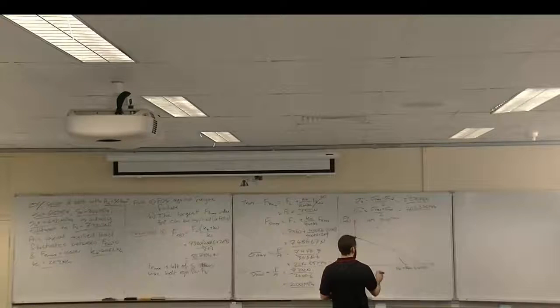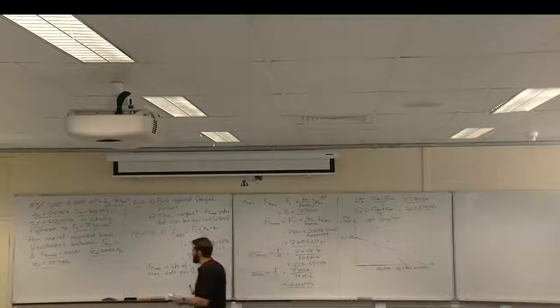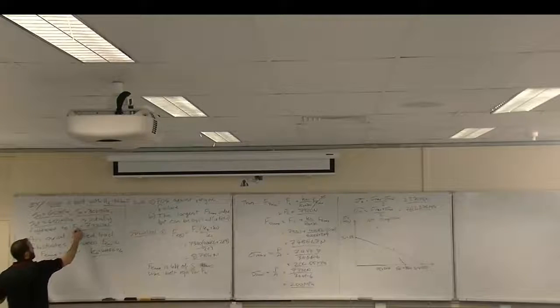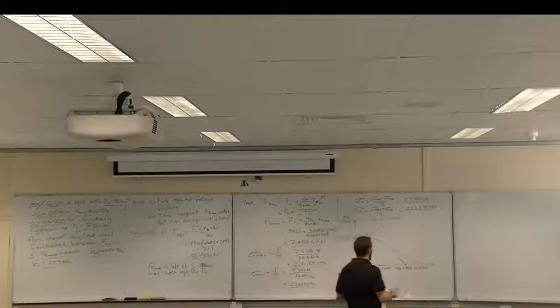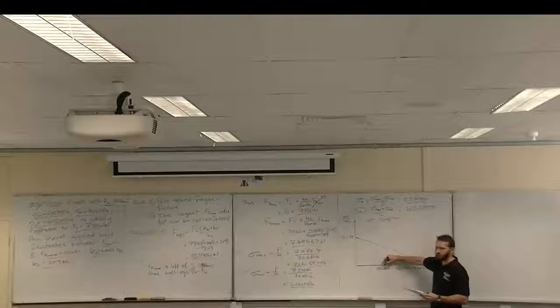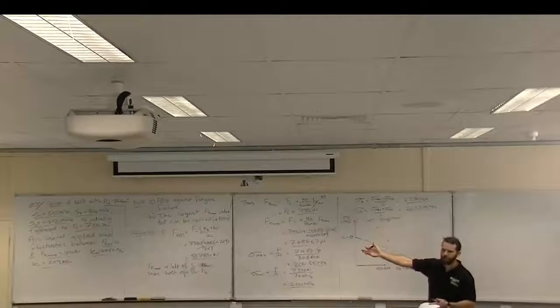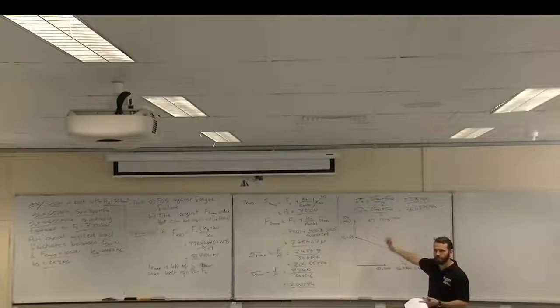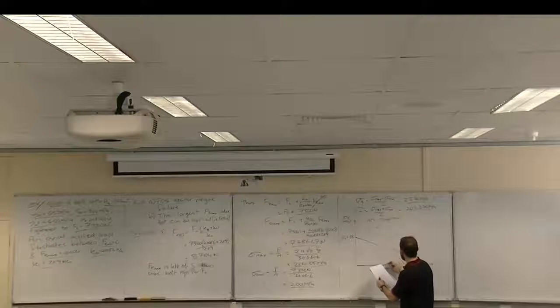Alright, so our intercept starts here at sigma, whatever the factor of proof load, sigma i, and that's 200. Which you can calculate, firstly we know from sigma min, but secondly you can calculate just by taking F_i and dividing it by A_T, which is 200. Alright, and so that's where we start on our load line. We are loading between 0 and something, and so that tells us we're going up at a 45-degree angle, so our load line is up like this.